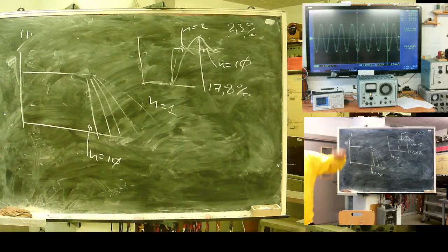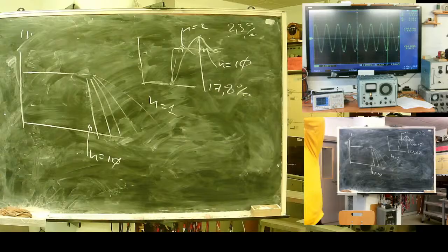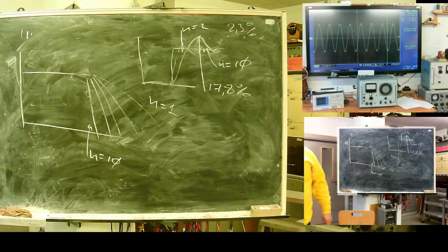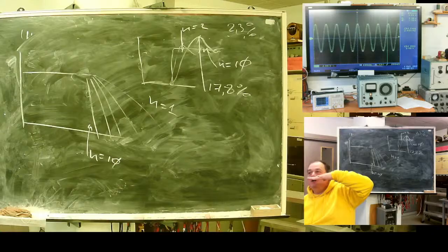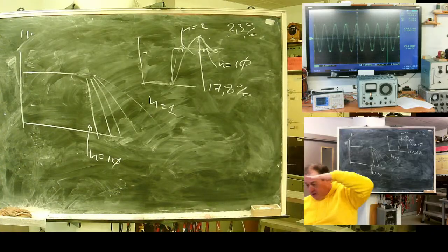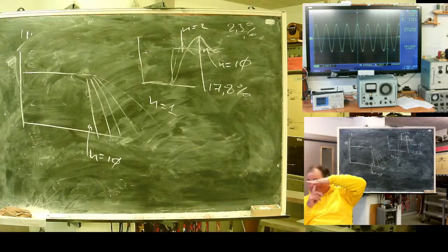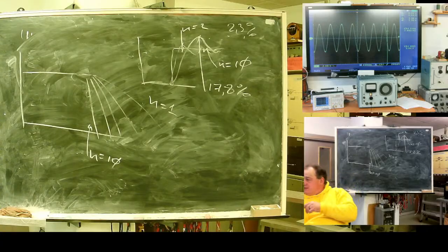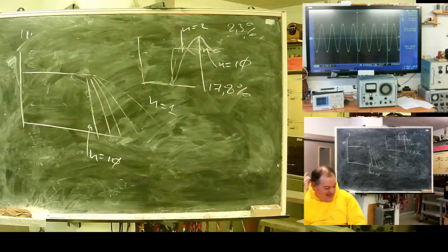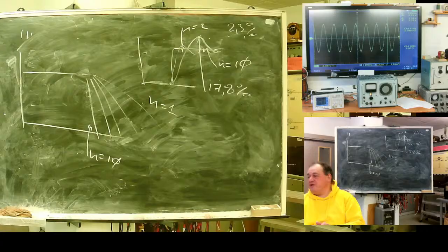Butterworth offers us a nice line at the operation range and a fast drop. What's good? It's uniform. In case of frequency shift, we can be sure that our preprocessing part will not disturb us. And it offers good cutoff. The simple RC design had an error of 20-25% for fifth harmonics.